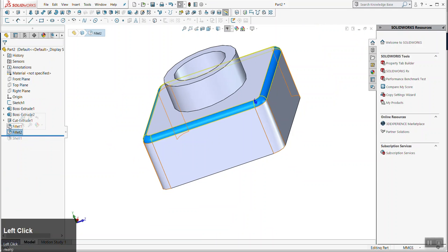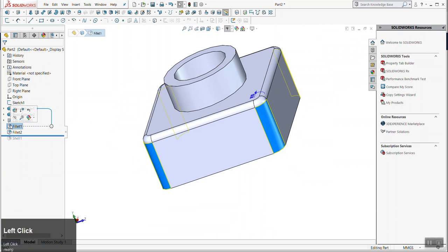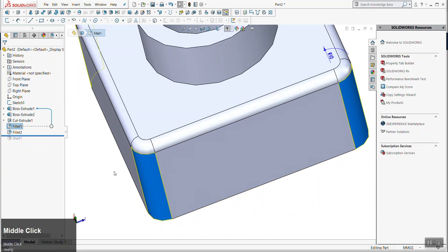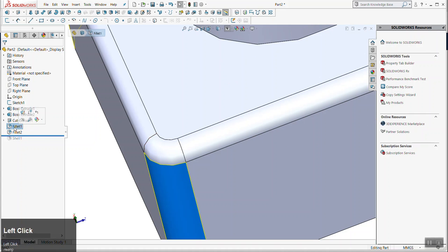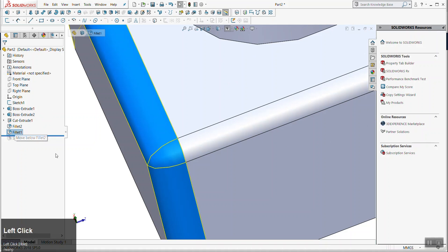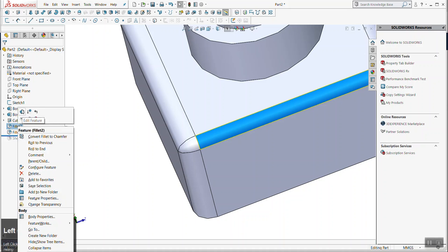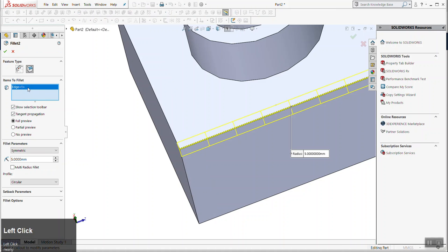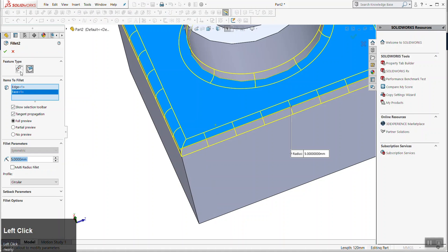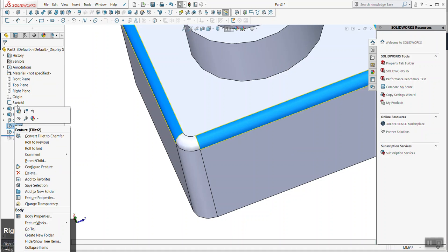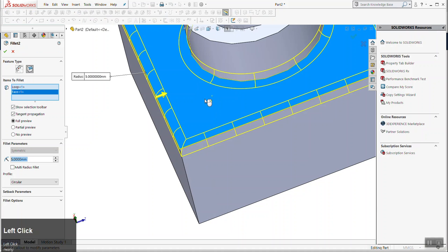So now if I rearrange these fillets, let me see if I can think. Look at this nice corner here. That's a pretty corner, unless you guys disagree. If you disagree, I'll show you. Oh, I guess that's not. Oh, you know what? That's funny. Let me redo this. That's what I was expecting. Oh, it still works. Okay. The order in which you fillet is important.